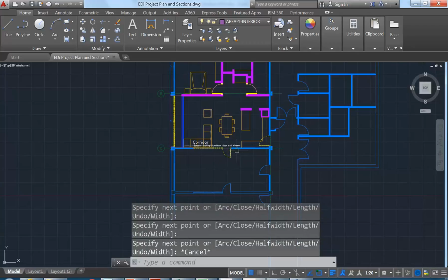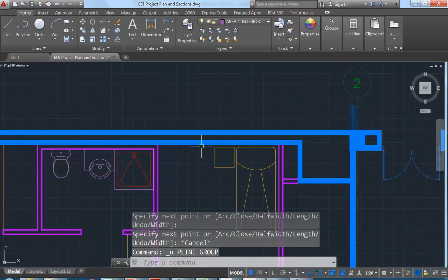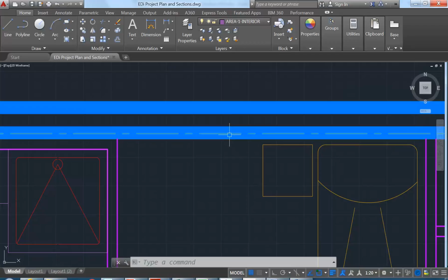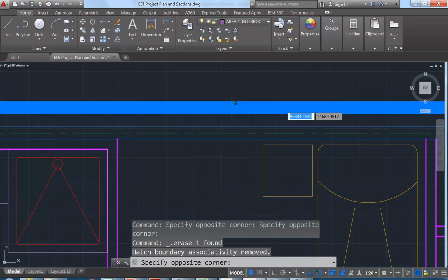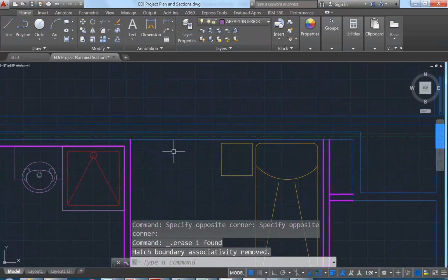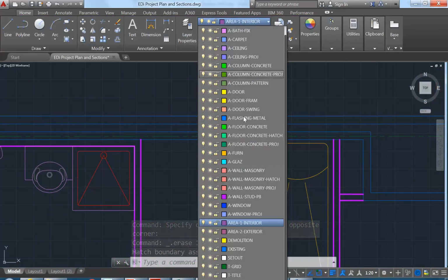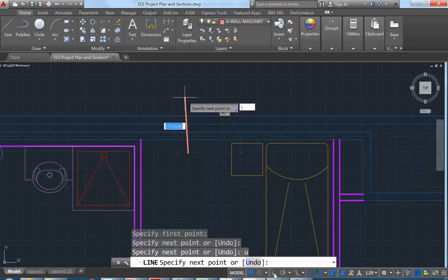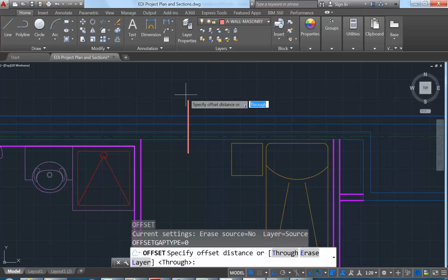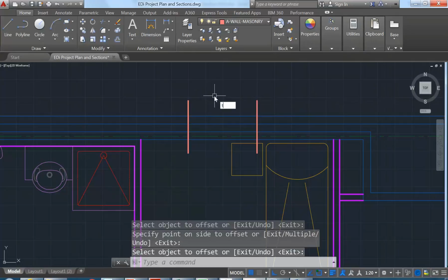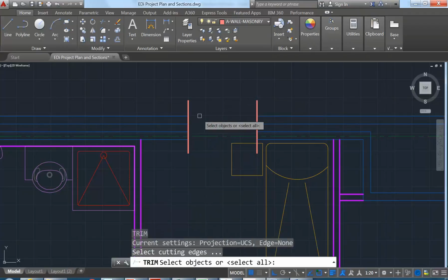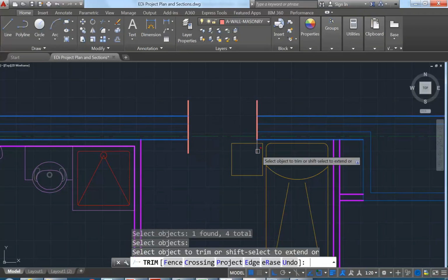And actually, sorry, to do this more accurately, I'm just going to maybe put in the windows, because I haven't drawn the windows in yet that I'm going to be punching through this wall. So I might quickly put those in as well. So I'll delete my hatching, and it doesn't need to be perfect as long as I've got a rough idea, because this is just a rough costing. Just make sure I've got ortho on there. So trimming all that away, that'll later need to be shown as demolition as well.